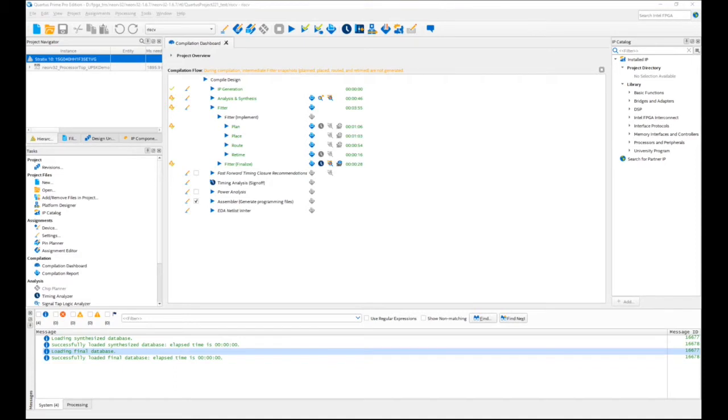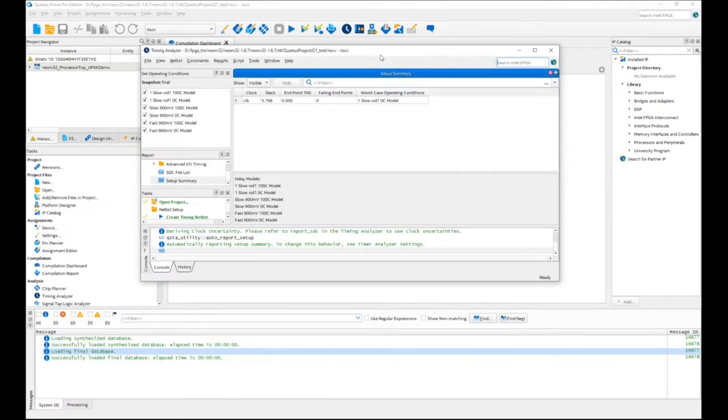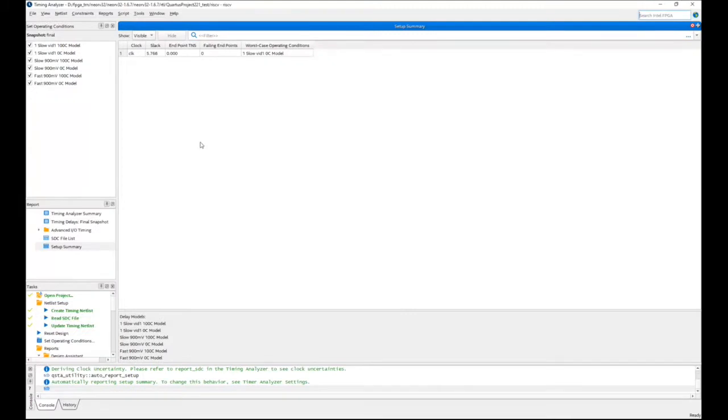But in Pro, and I'm pretty sure that Standard works the same way, when you run timing analyzer, it will run for all of the temperature and voltage variations for the particular part that you've currently selected. So if you go to a different part like you have there, for example a -I6G, you'd have to go in and select that part and then run that, and then the reports will be generated for all the different voltage and temperature variations. Yeah, you can switch.